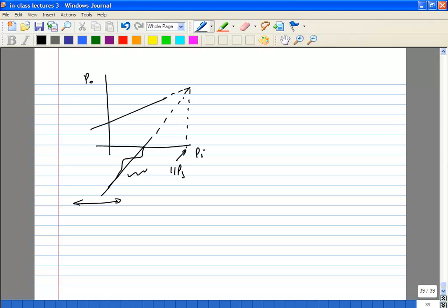The reason is this kind of nonlinear behavior can happen when you operate at low powers, and that will artificially give you a feeling as if the system is very linear because we have used IIP3, but it's really not so.